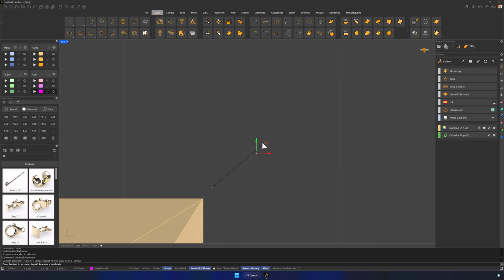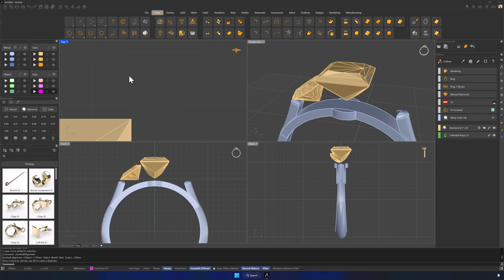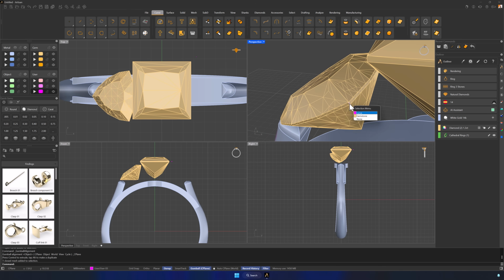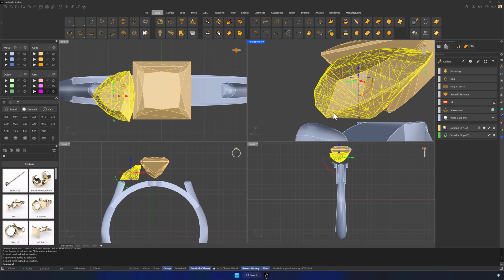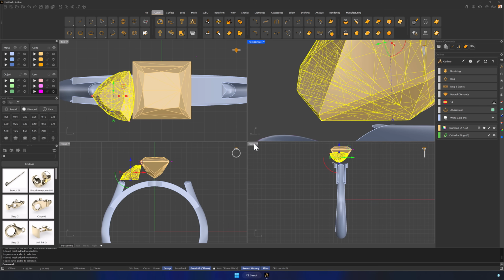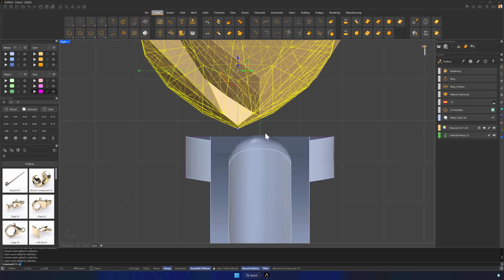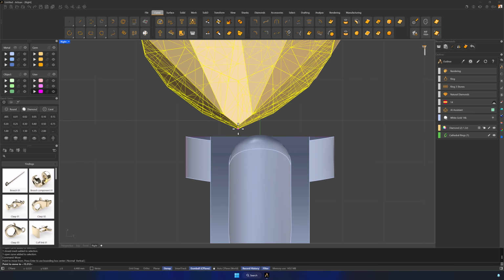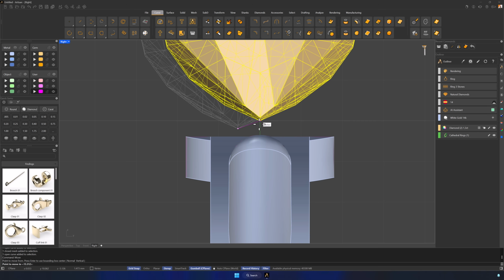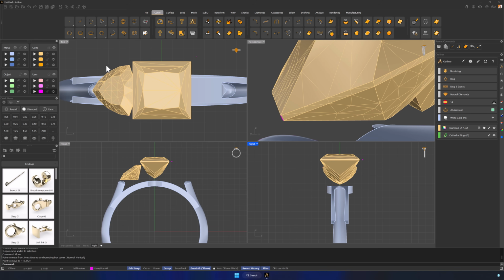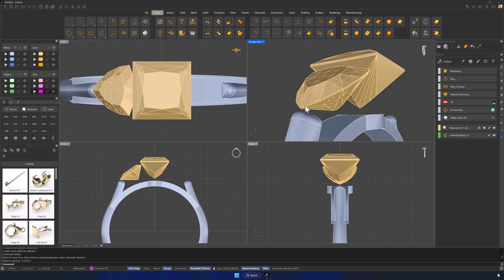Now, look at the other gem. From the top view, it's not centered because when we rotated it, its pivot wasn't aligned with the center of our working area. To fix this, select both edges of that gem and the gem itself. From the right view, type Move. Select the bottom vertex of the gem, and with Grid Snap active, press Shift to move it to the same height, but now centered along the axis. This way, the gem is correctly centered together with its edges.